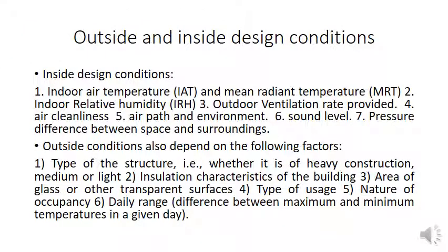The factors contributing to inside design conditions are, number one, indoor air temperature, then mean radiant temperature, these are the two temperatures basically. Then relative humidity. Due to the presence of human beings, the internal heat load in the inside design condition also increases. If more occupants are there, the load will be higher. Then the outdoor ventilation rate provided; ventilation rate means the total air changes per hour from internally and externally to the room. Then air cleanliness and air path environment, and in fact the sound level. Apart from air cleanliness and air path environment, if there is some continuous generation of sound, it also plays a role in determining the inside design condition.